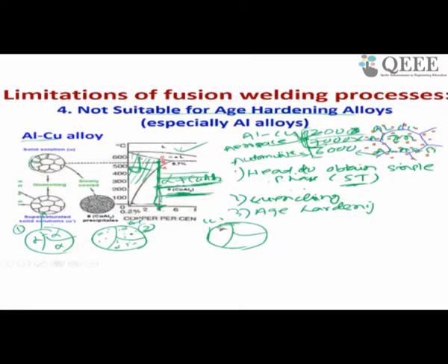The dislocations will move above the yield point because it is the plastic deformation zone above the elastic limit. Then the dislocations will move from one grain boundary to another grain boundary along the slip plane and slip direction. Dislocations can move easily because there is no obstruction in case 1. In case 2, what will happen? Case 2 already has this kind of microstructure.